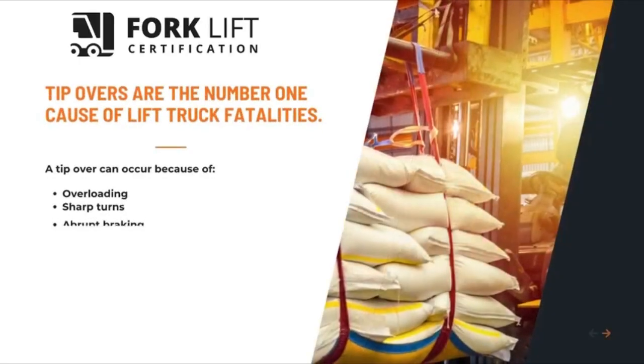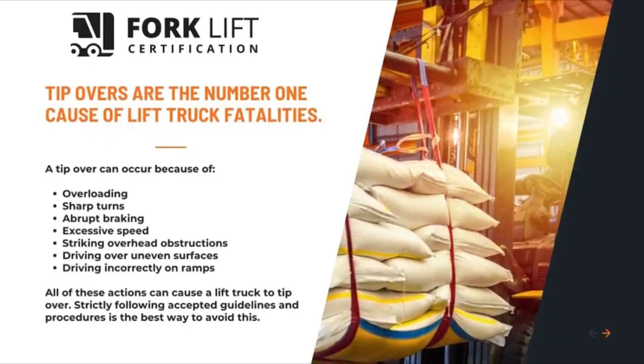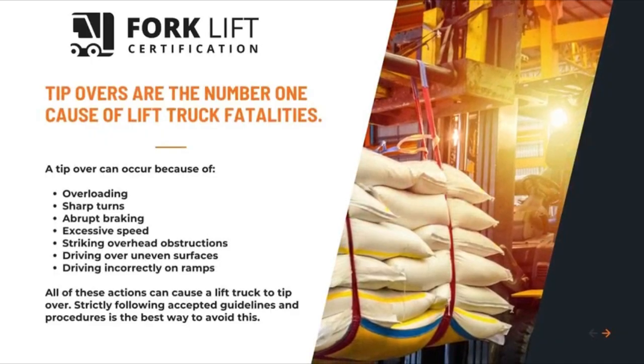Reasons leading to a tip-over. Tip-overs are the number one cause of lift truck fatalities. A tip-over can occur because of overloading, sharp turns, abrupt braking, excessive speed, striking overhead obstructions, driving over uneven surfaces, driving incorrectly on ramps. All of these actions can cause a lift truck to tip over.